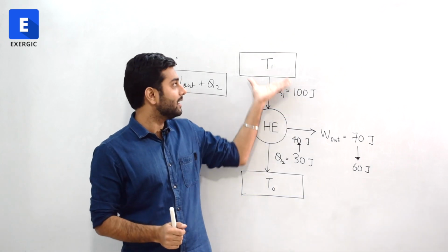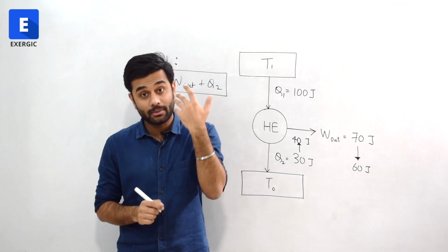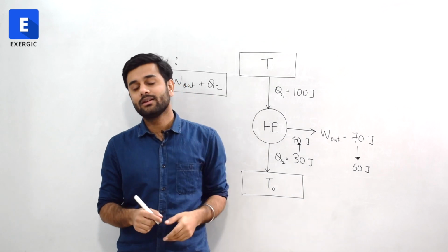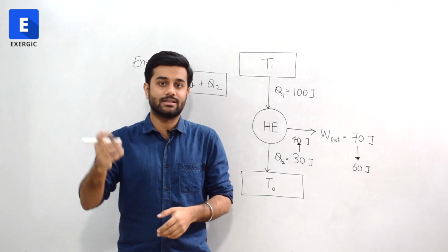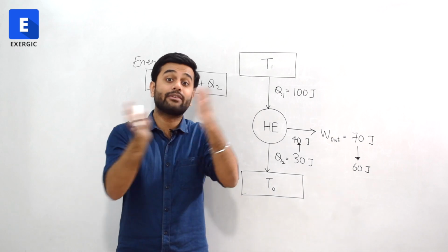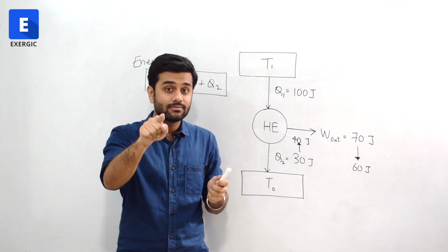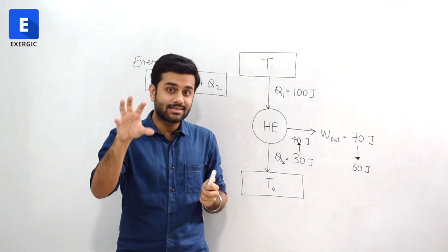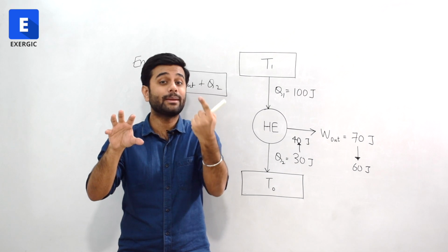This heat which was available at T1, we know how to calculate its available energy. I am repeating it, I think for the third time: using a Carnot engine, or totally reversible engine, that work output will be its maximum available work. And this heat engine is to be installed between what temperatures?